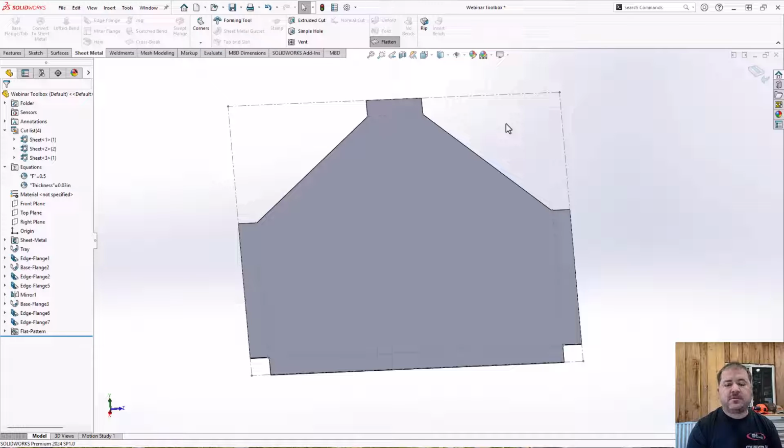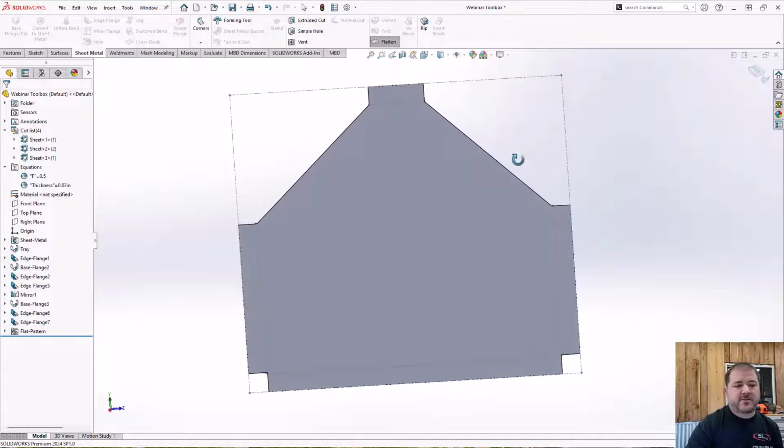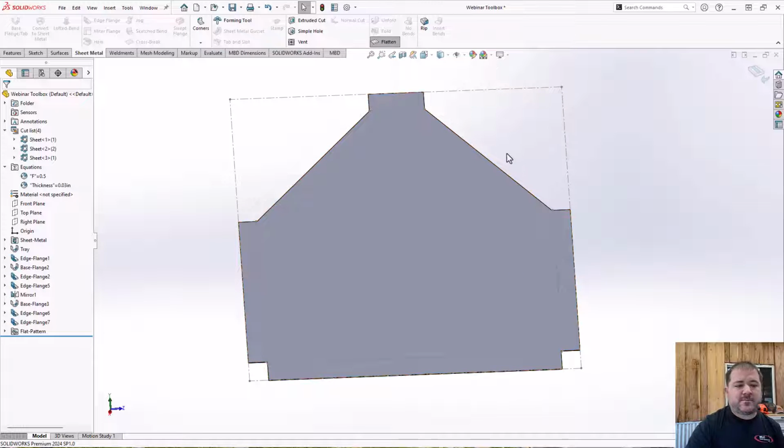The best thing you can do for your shop is to take a sample part, just a piece of material, measure it very carefully, and then bend it. And then measure that. And you'll come in here to SOLIDWORKS Sheet Metal, and you'll create the same part, and you'll make it flat, and you'll make it bent.